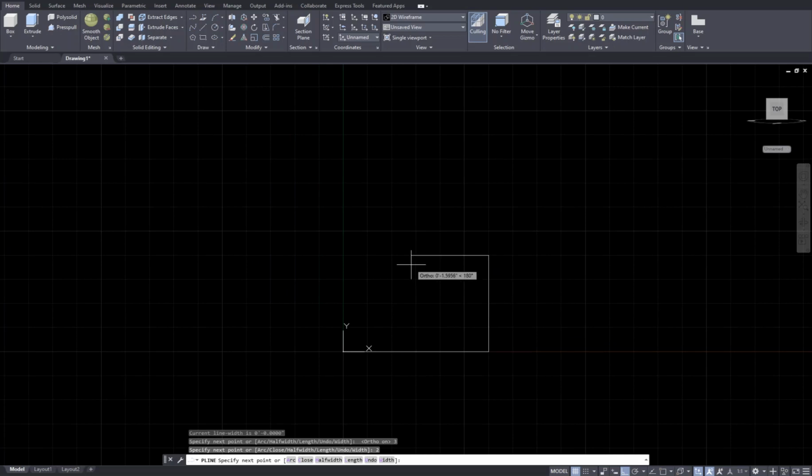Now I'm going to turn off the ortho, and object snap is on. The object snap shows me where the middle point of the line is. At this point I'm typing @. The @ tells the computer the beginning of relative coordinates, and we want to go 1.5 inches to the left.